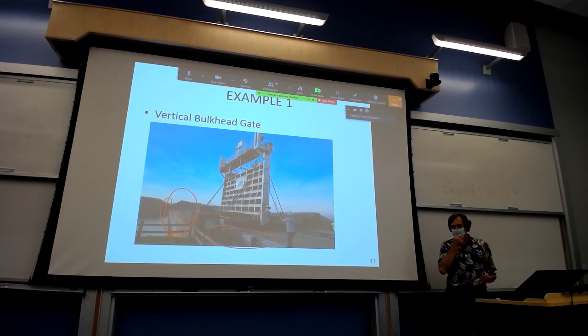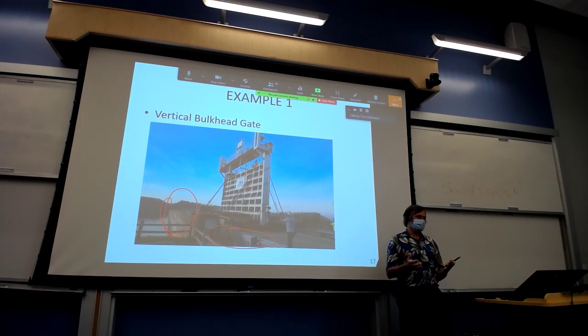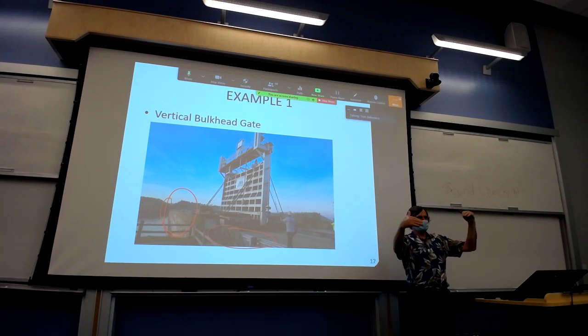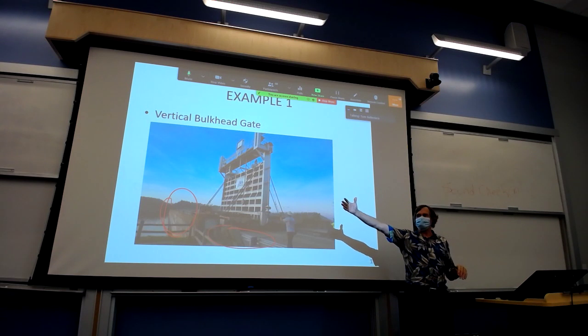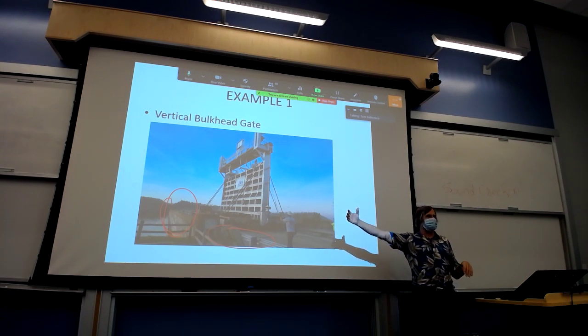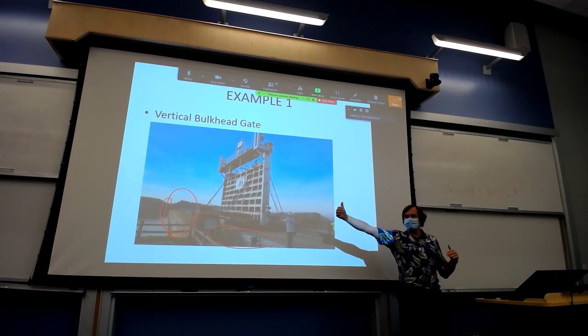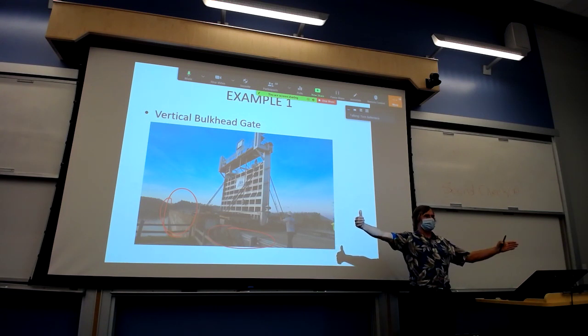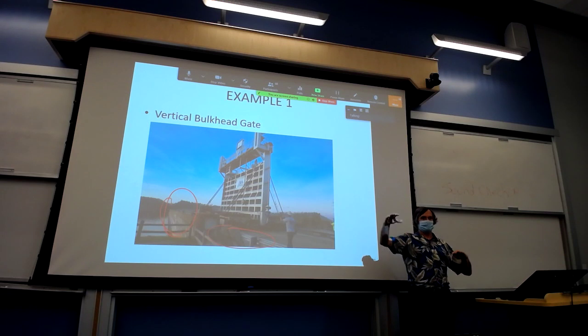So typically, if you're doing, for example, flood control, the gate's open, and whatever comes in the reservoir goes out. But if you notice a big rainfall event's happening and you want to control the flood, you shut the gate, and downstream you have no water going through the dam now, and all this flood water going in and filling up the storage. So you have a lot of water on one side of the gate and none on the other.